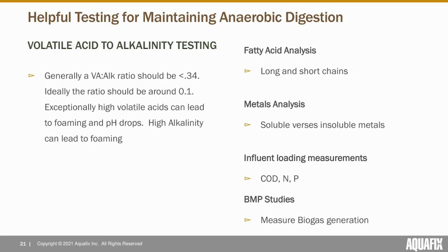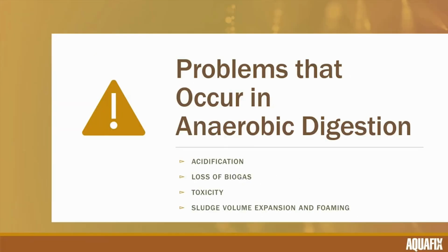And another interesting tool, if you are attempting to correct or supplement your anaerobic digester, is a BMP study, which tends to be fairly simple. You fill a jar, and you have to be able to measure gas and mix it for a full month or so. Essentially, you're filling little bottles with anaerobic feed sludge and an anaerobic culture, and over the course of the month you can compare how the methane quality and quantity has varied depending on different additives, because it can be very slow testing them one at a time in your process. This enables you to experiment with a bunch of different changes in your process at the same time to measure how they affect methane, which is a very good indicator of anaerobic digestion efficiency.